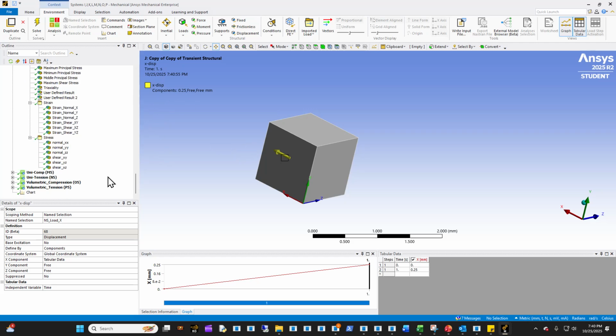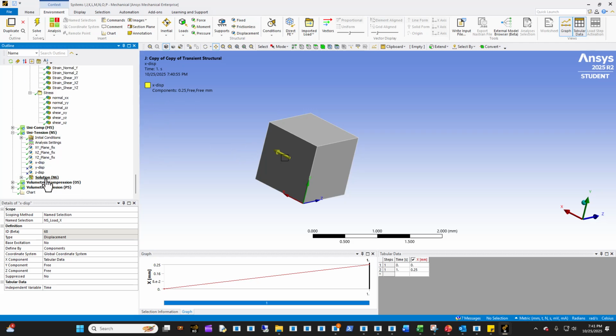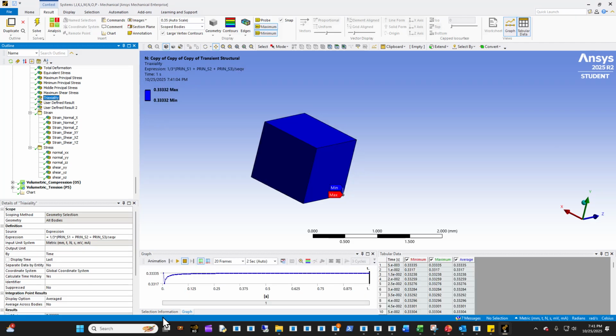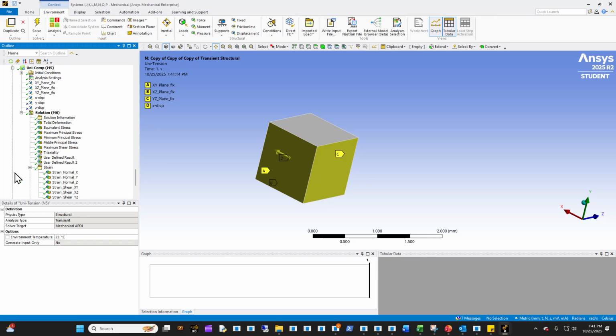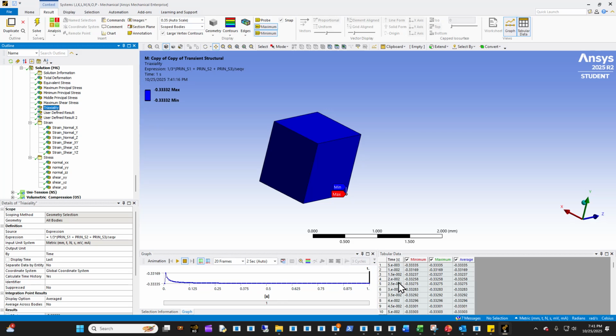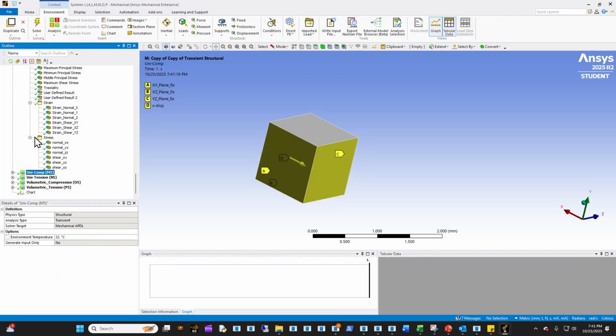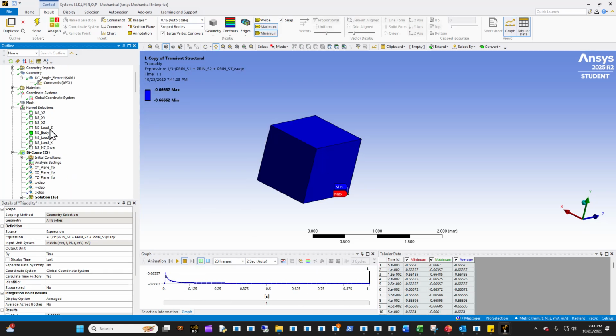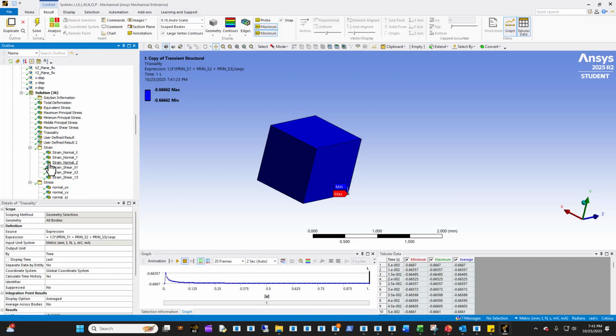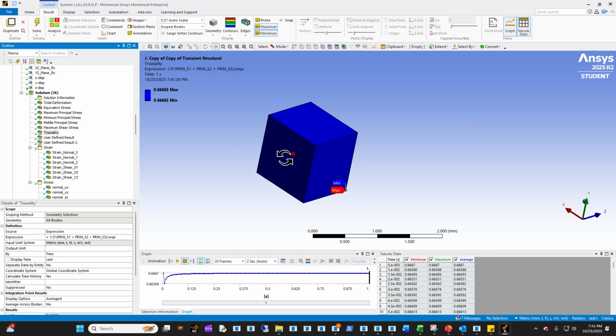And then you can see in uniaxial tension, I actually plot a triaxiality down here. Triaxiality is 0.33, right? This equation right here takes your hydrostatic stress over your von Mises stress to give you the triaxiality. Uniaxial tension gives you 0.33, and uniaxial compression gives you the same triaxiality magnitude, negative 0.33 in that case. And then obviously biaxial tension and biaxial compression are going to be 0.66, right? So this is negative 0.66, and down here is going to be positive 0.66.